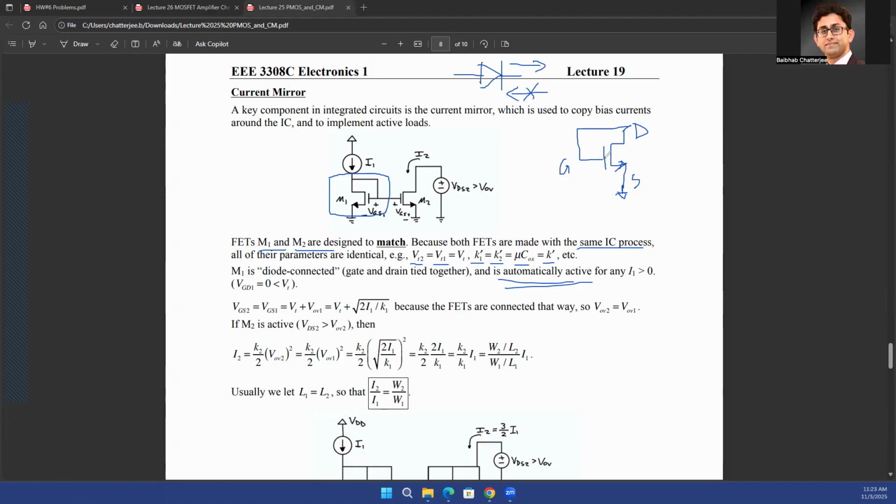So you're already connecting the gate terminal and this terminal. The transistor, let's say it has 3 terminals, neglecting the body terminal for now. You have 3 terminals, and you're connecting the gate with another terminal over here. And in that case, if the drain terminal is at a positive potential, and this is negative potential or ground, the current flows from the drain to source, which generally happens in a transistor as well.